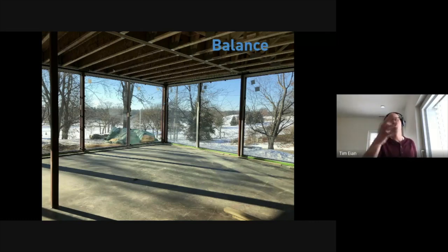The reason why I do show this photo is because on the flip side of that coin, we do pick up some design freedom. And so when we have a fantastic site like that one was, with an incredible view in the middle of the urban core, we can allow ourselves a facade like that and take advantage of all that and not pay a huge penalty for it. And that is one of the, again, more comfort-related pieces that come out of passive house. Now, architecturally, we can do some stuff that in conventional design would be a no-no. You would have to put strip vents all the way across that, or put a fin tube across the bottom to make this bearable on any level.